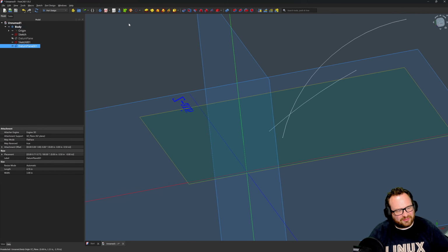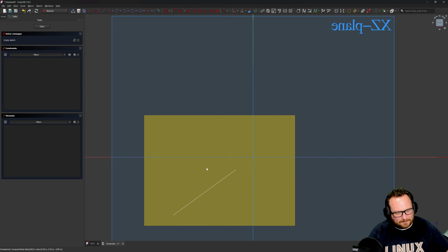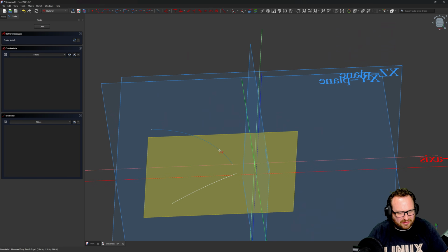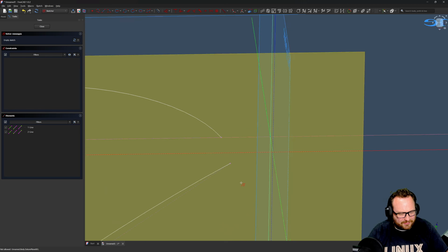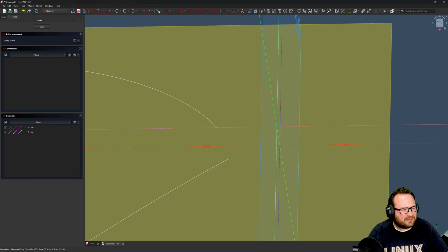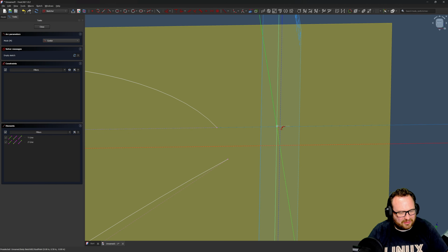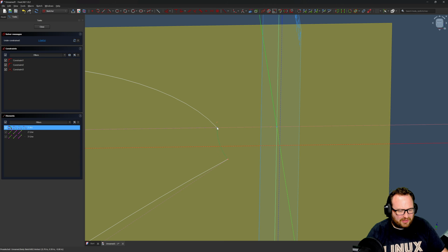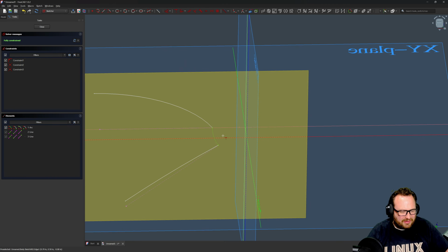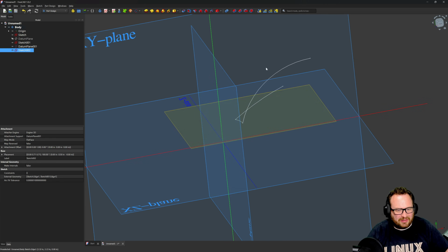So we're going to create a sketch on this plane, again, clicking the sketch button. Now I can create this create external geometry button, and I'm going to import my two arcs. And then I'm going to create an arc. There's my origin, right? So I put my arc center right on my origin and go from one point there to the next point. Now we're not coincident, are we? So I'll say C for coincident and click on both of those points, and then we'll snap in the right spot. Okay, excellent.